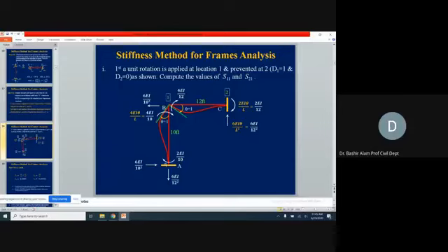Now shear and moments we found, but now where is this 6EI over 12 square coming from? Again, if you remember, at this B joint we were restraining only the rotation, meaning it was not capable of transferring the moment, but it can still transfer the shear and axial forces. So here, if you remember, it was downward 6EI over 12 square. So for member AB, to balance this joint, it will become upward 6EI over 12 square.